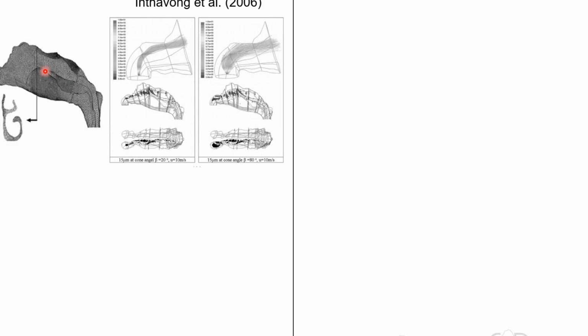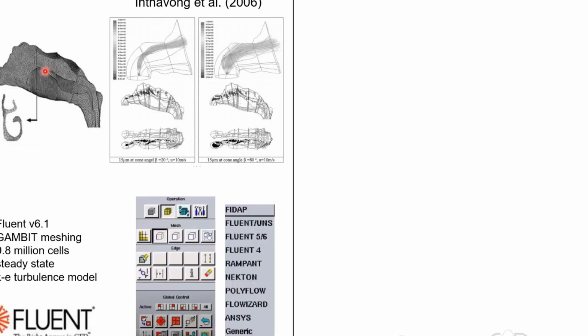Beforehand, structured mesh was the only way, but now we used Gambit at the time to do the meshing, and this had a wonderful wrapping and Delaunay triangulation method that allowed us to do the tetrahedral mesh. For those that have a bit of nostalgia, you might look at this and go, oh yes, I remember that, whether it was fond memories or not.